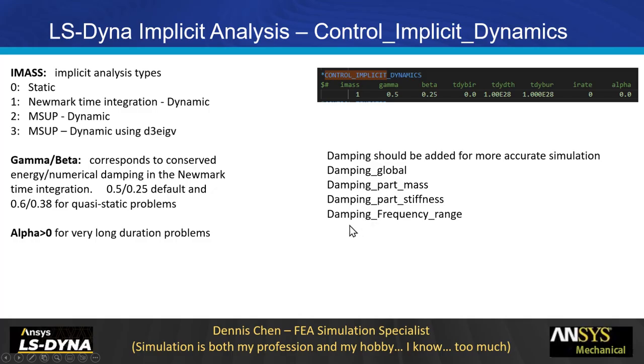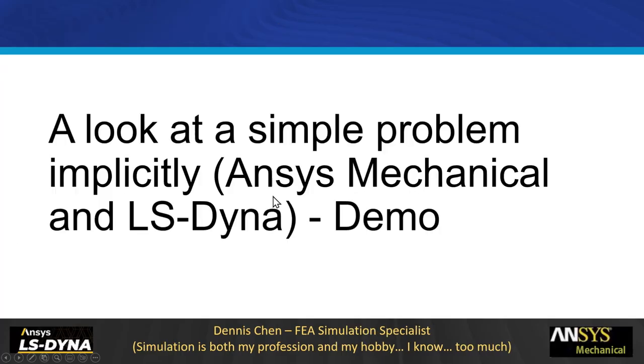Okay. And of course, in here, the key parameter is the I mass parameter, right? You set it to 0 or set it to 1, given whether or not it's a static problem or a dynamic problem. Okay, so this is the basic concept.